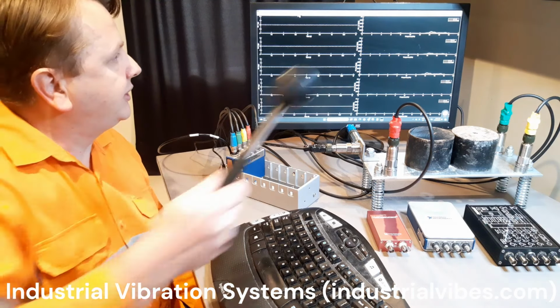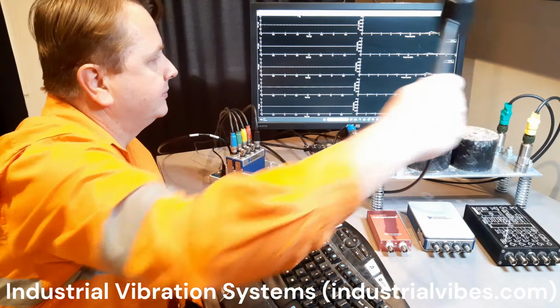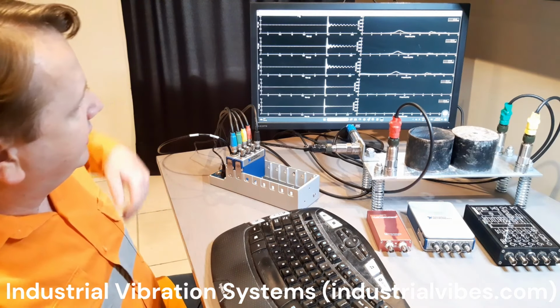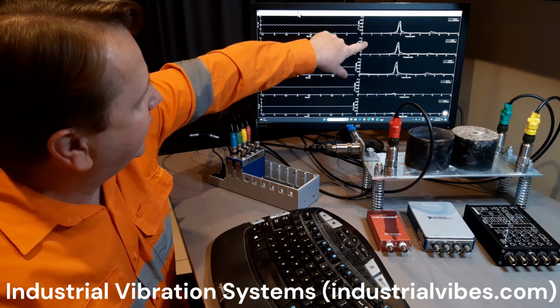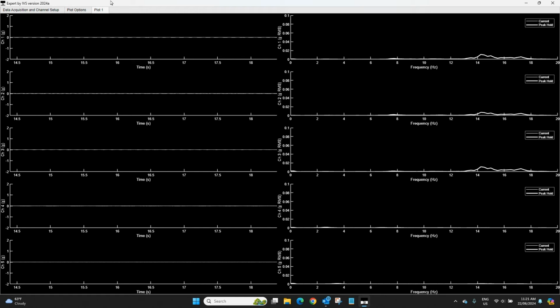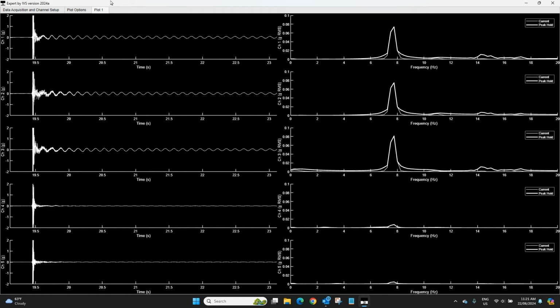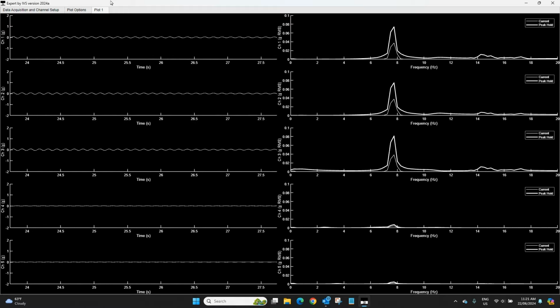Okay, so I'll start with a vertical impact. Now channel 1, 2 and 3 are vertical, which is why we're getting a clear signal on those first three channels there. And that strong frequency there would be the main bounce mode.